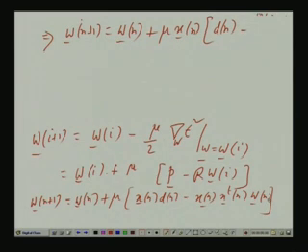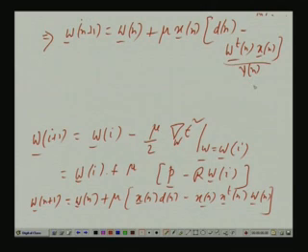And x transpose n w n is the same as w transpose n x n, because A transpose B and B transpose A are the same. And what is w transpose n x n? At any index n, w transpose n gives the filter coefficients w 0, w 1 up to w L. They multiply the elements of the x n vector. So what you get here is the corresponding filter output y n at index n, and d n minus y n is the error e n. So that gives you this algorithm.